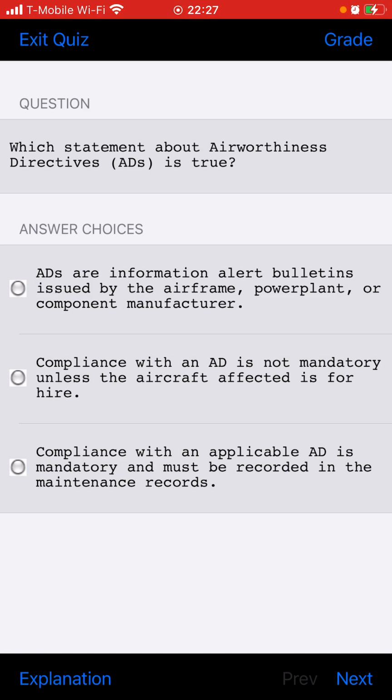What is the function of ventilating air in a combustion heater? It is the air that is warmed and sent to the cabin. What are sources of ventilating air in a combustion heater? A blower, fan, or ram air. What can be used to static check a manifold pressure indicator? Current atmospheric pressure.